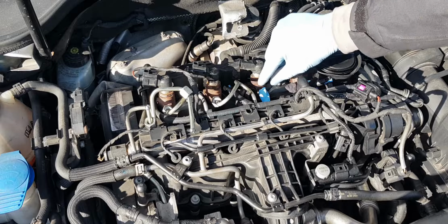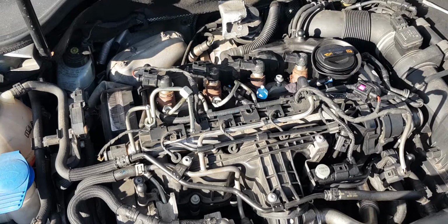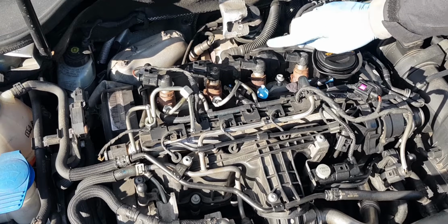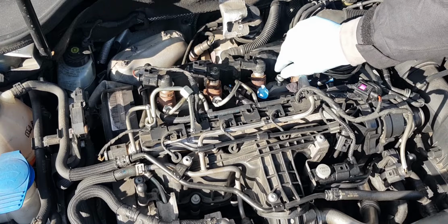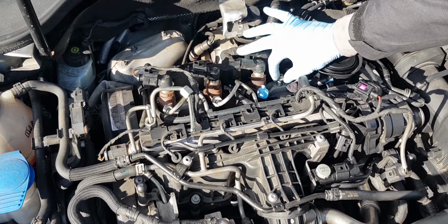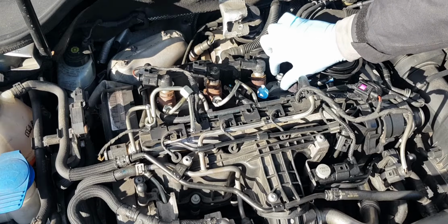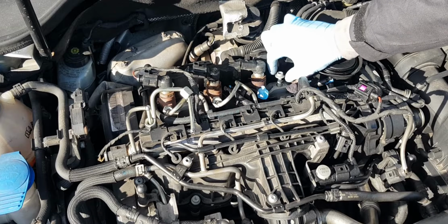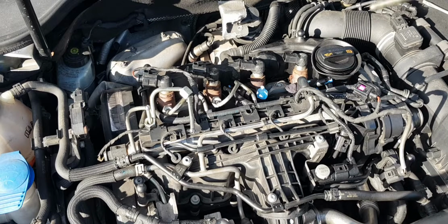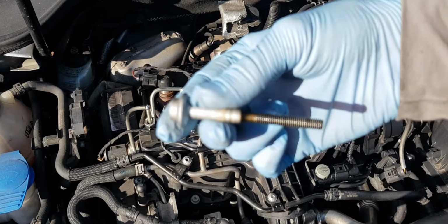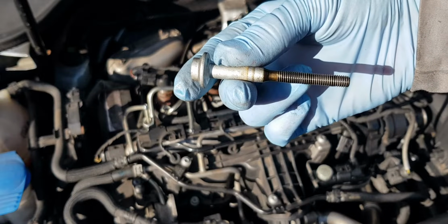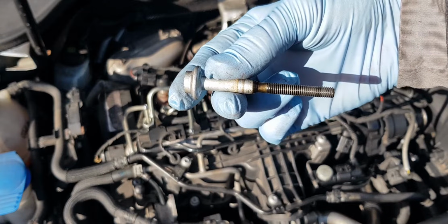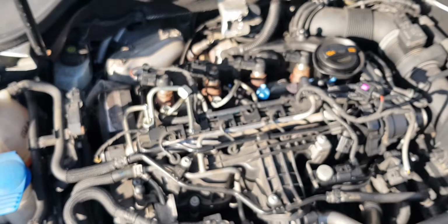Obviously there's only one way they can go, because at the end of the day, you can see your hoses, your wiring, the plugs are facing, the pins are facing this way to the left of the engine bay. So again, this bracket here holds them in place, so you can't really go wrong. That's the bolt. I have a new bolt that I'm going to use, and I think the correct torque for these is 8 Newton meters plus 180 degrees after that.